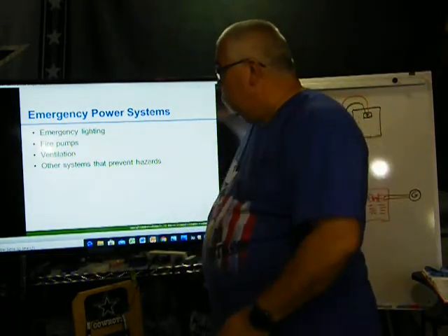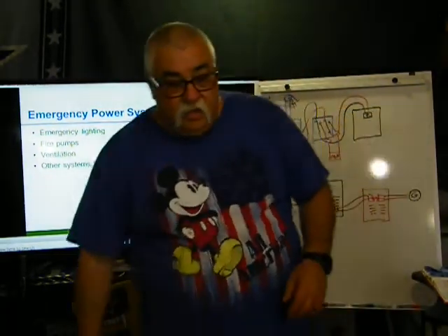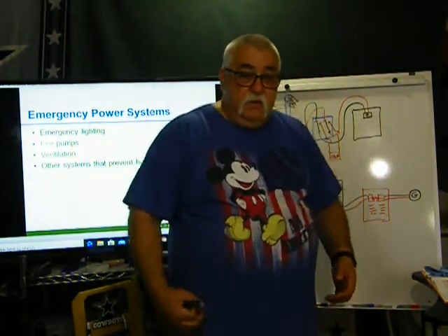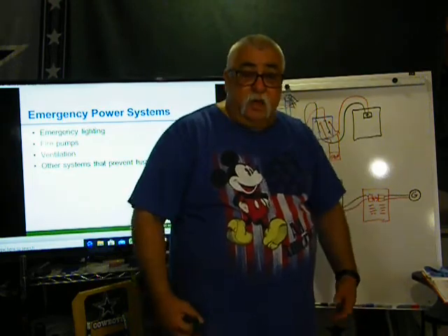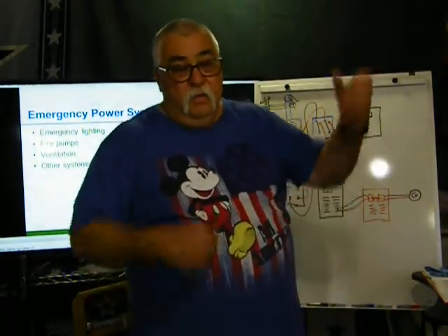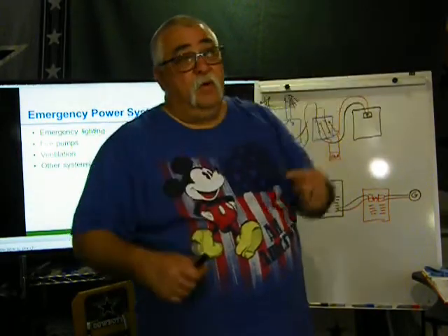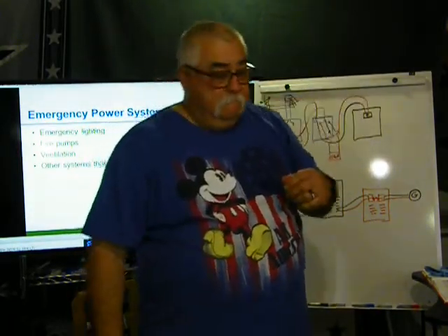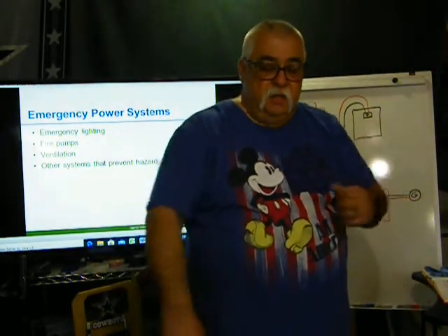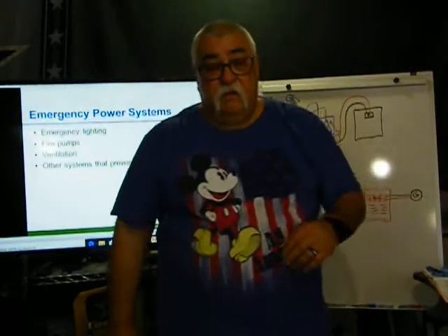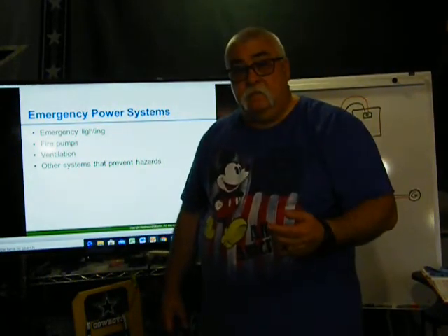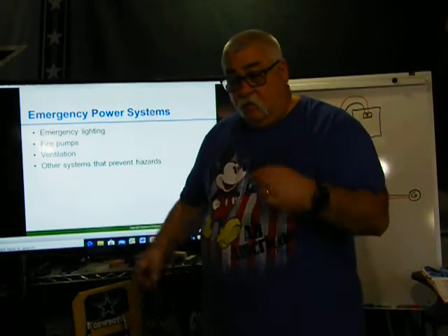And that's what happened in this instance. They said that the gear that they wear is all leather, and leather's not waterproof, so obviously their shoes were wet, and they're standing on the ground throwing water, and one of them, when they were making the vent holes, I guess they hooked something up in the attic. He hooked up to the DC side of the inverter, the solar panels on the roof, and he got shocked. Okay, this is before this one was done.